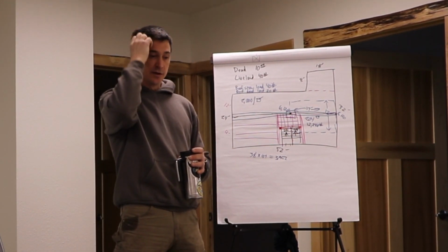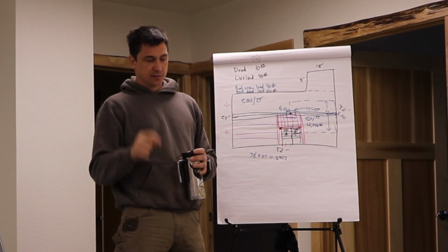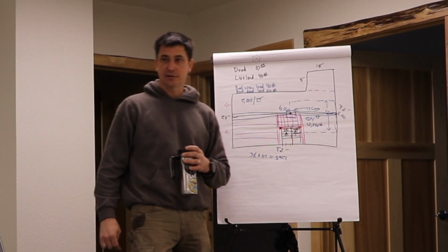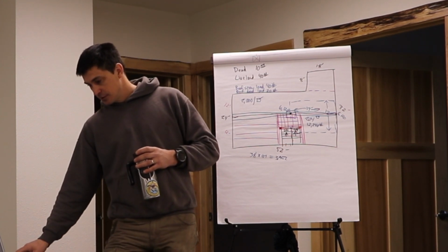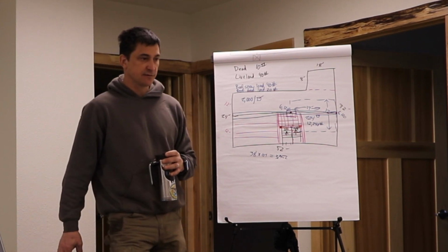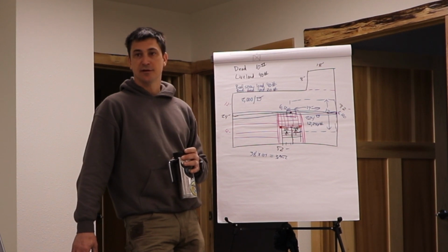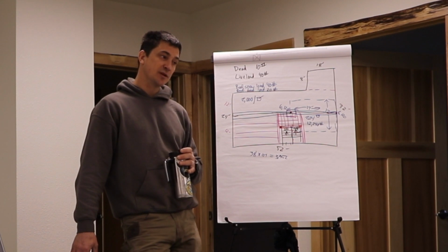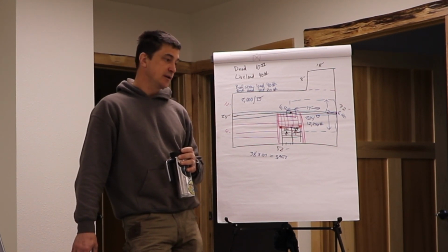Maybe we have to plan in some spots to put a chase for them to run return air ducts and supply air ducts. So that's your job as the contractor to make sure that all of the other trades can get their stuff into this building. And you want to figure that out before you start building in case you have to change something. Maybe it means we need to look at going to radiant heat on this thing.